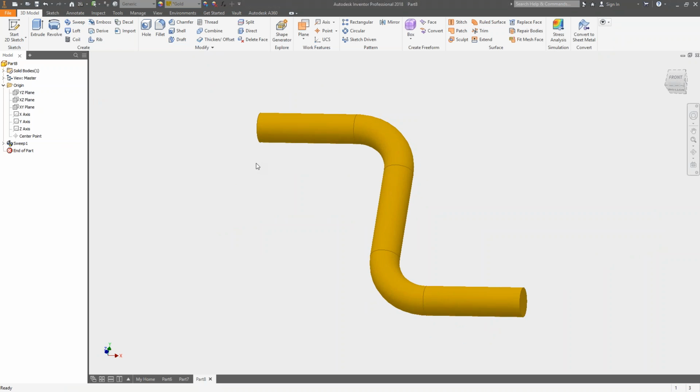So in some cases you're using 2 and 3 sketches. You might be doing a Loft command, which we'll talk about next week, where you have 2 sketches and a path. So you have 3 sketches to create the geometry you want. So it's not always sketch, extrude, sketch, revolve. You might be mixing and matching those tools.